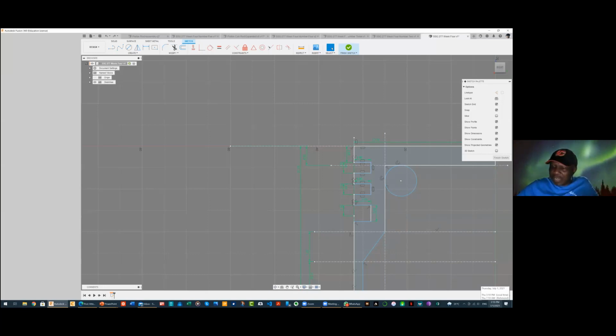I still seem to be having another chapter. So how do you draw real lines from construction lines? For instance, this line here is a construction line. If I want to make it a real line, I go back again and just press X. So I've turned this construction line into a real line now. But I don't like that, so I can just undo. So you can make a real line a construction line, or a construction line a real line. All you do is press X after you have marked that line.